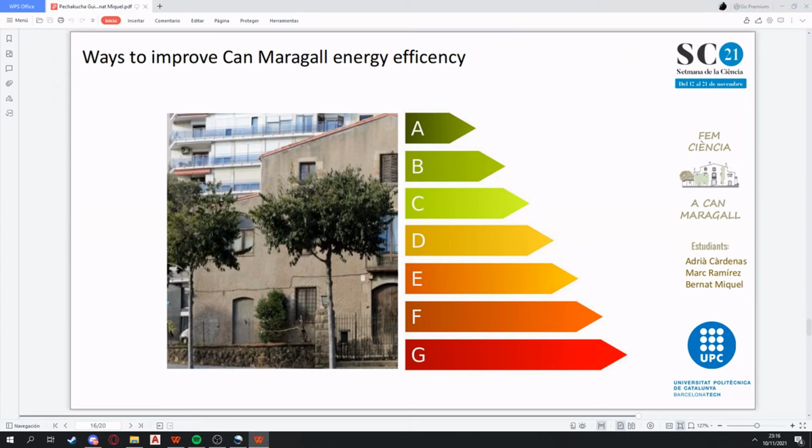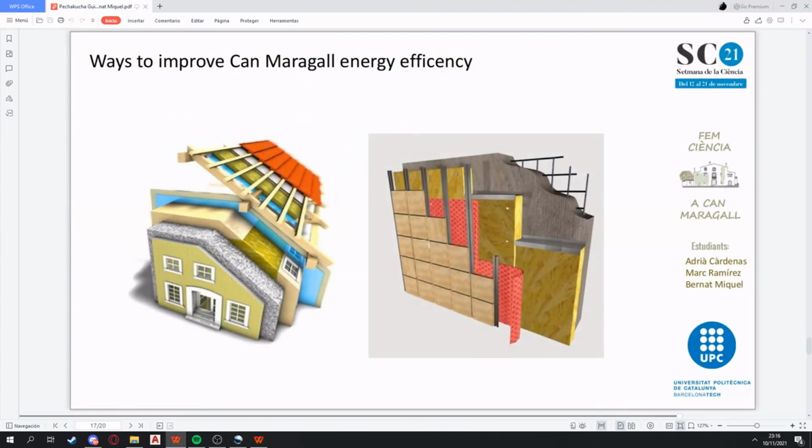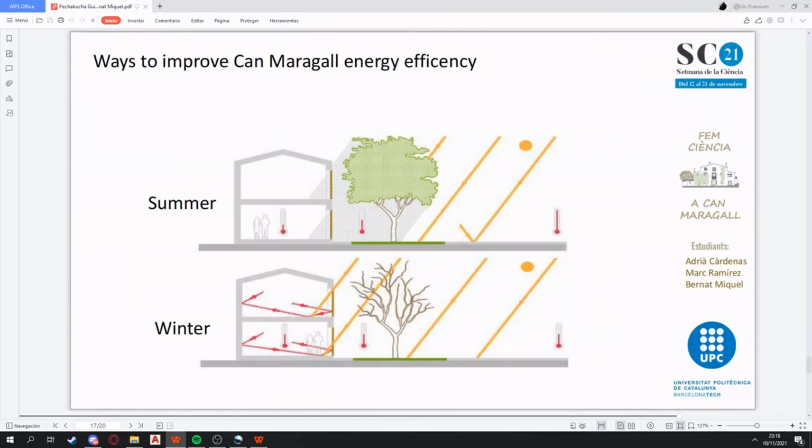The thermal inertia of the materials that make up the thermal envelope is a good strategy for controlling energetic demand in indoor spaces, especially in climates with a significant temperature variation between day and night. Thermal inertia provides passive heat accumulation capacity.